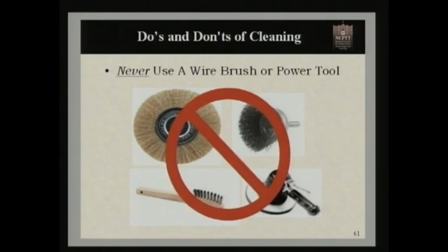These are things that have been used in the past, and occasionally they pop up where people will say, oh, muriatic acid works great. And this does a lot of harmful effects to the stone by removing that initial first layer of material. So one of the things that we want to talk about, the nevers of cleaning, is we never want to use wire brushes. Now this is something that we hadn't really seen before until fairly recent, in the last couple of years. It's been broadcast on the internet, and people have talked about on some of the genealogy forums using grinders with wire cut brushes or drills with wire brushes to clean monuments.